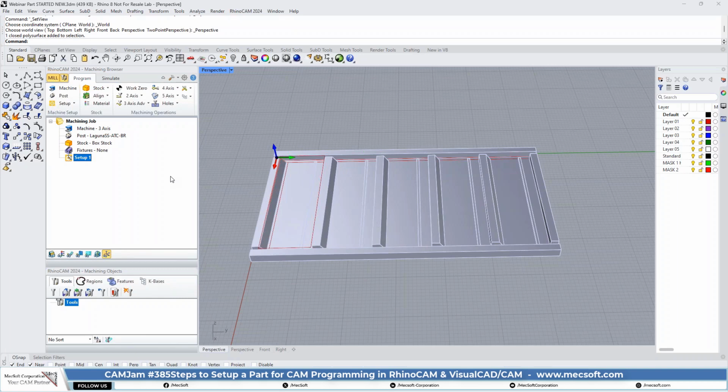So you would want to keep that in mind and orient your part exactly as you would orient the actual workpiece on your machine. So that's very important to do, actually. Yep, that can mess you up completely if it's not oriented correctly. That's why there's basically 2 or 3 steps at the beginning of the project that you need to do before you do any programming, and that's one of them.